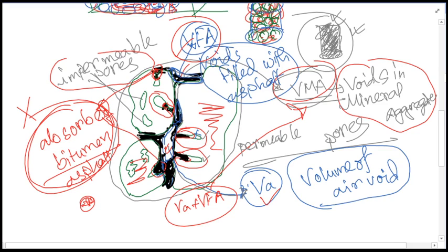And as we have a limited percentage of asphalt content, in general the bitumen will not be able to reach the final portion of these pores. That's why some portion will still remain as empty pores, although within the permeable pores the bitumen will have penetrated up to some extent.